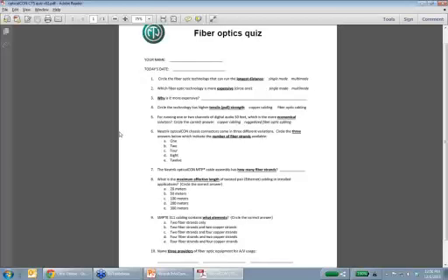This gets back to the point that we talked about. Number 6: Neutrik opticalCON chassis connectors come in 3 different variations. What are those? B2, the duo; C4, the quad; and E12, which is the MTP. I skipped over that MTP: the fact that MTP is 12 fibers in one strand is number 7. opticalCON MTP has 12 fiber strands in one connector.